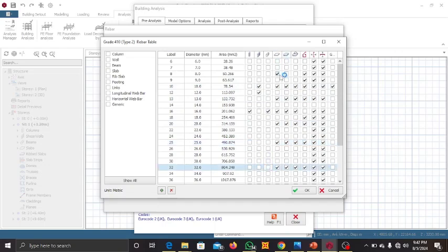For your slabs, we are going to be using Y12 for slabs. For rib slab, we are not doing anything concerning rib slab today, so we can leave that. For our footings, we'll be using Y12 for all our footings. For links, let's use Y8 and Y12. So uncheck others and just check Y8 and Y12.